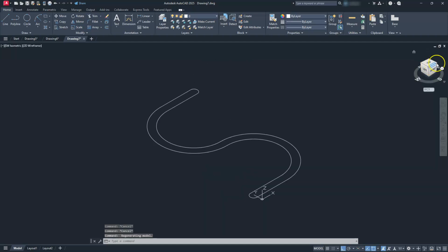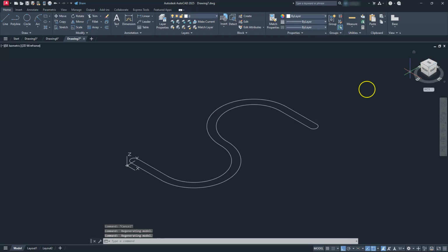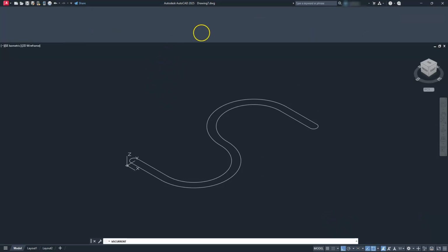So I select that on the corner here. I'm just going to rotate it around. Now I see where it says front, right, and top. Let's go ahead and switch AutoCAD over to 3D. Remember, we're going to do that with the little sprocket here. Click the fly up, go to 3D modeling. You're going to give it a second and the ribbon should change.